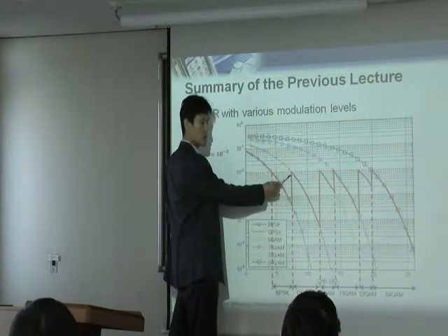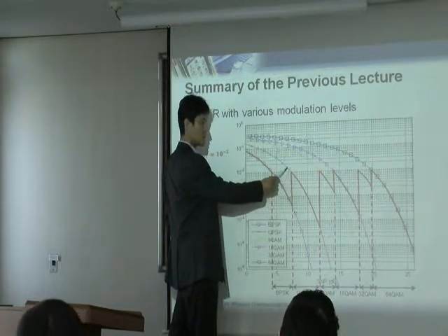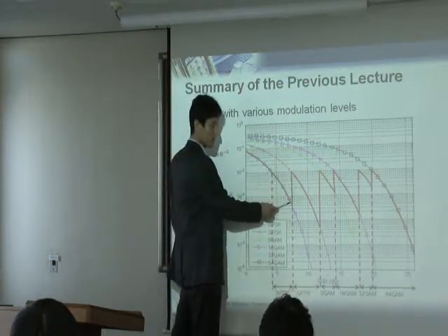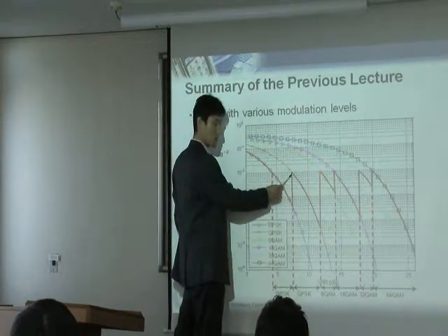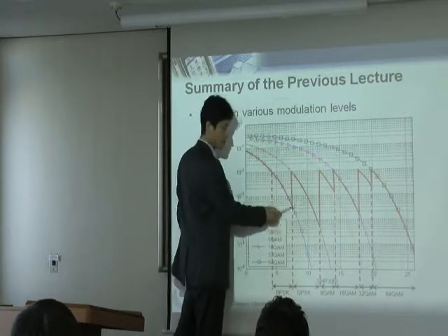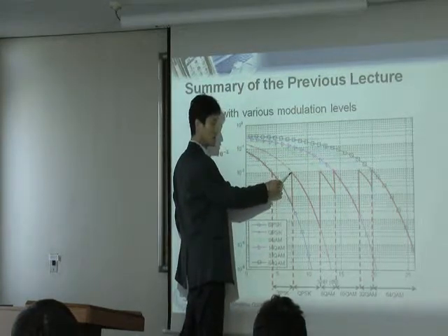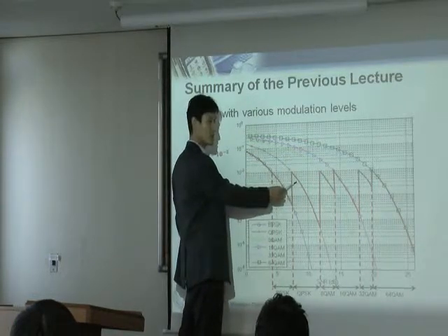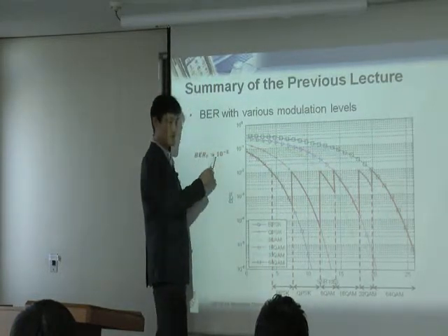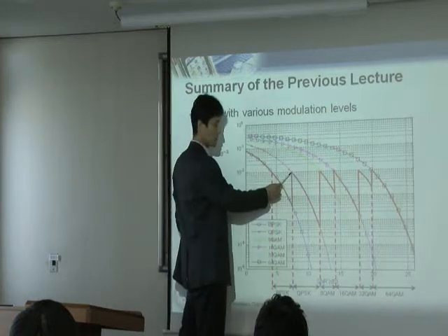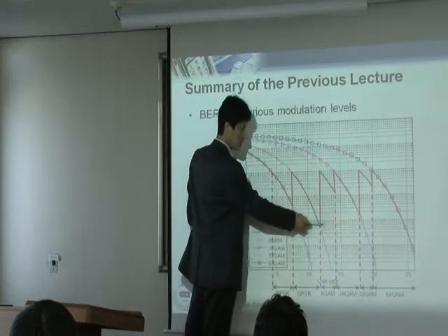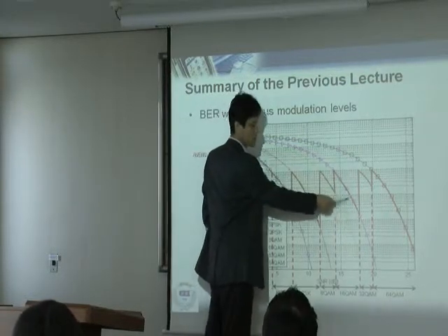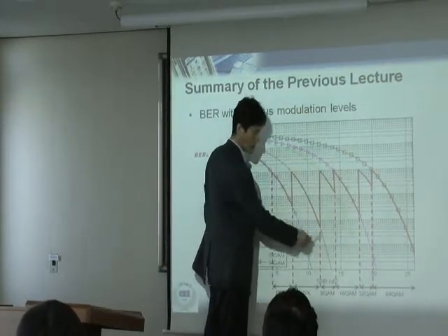So now you switch, because even after switching, QPSK can give you 10 to the minus 2. Instead of just going down, you switch so that instead of 1 bit, you can transmit 2 bits, and you also satisfy the target bit error rate. Then keep going down, and again you switch. Now you can transmit 3 bits, 4 bits. So that's how you decide this threshold.